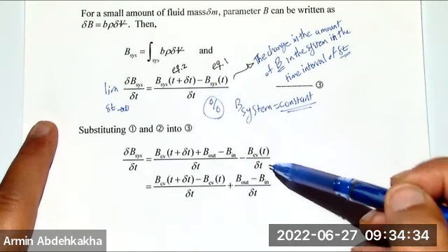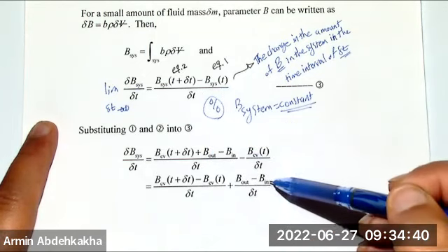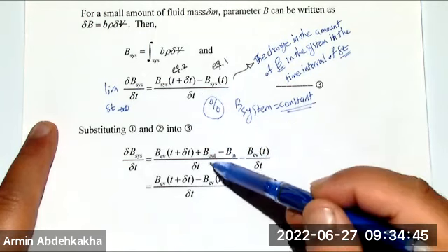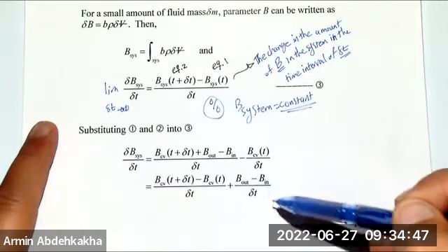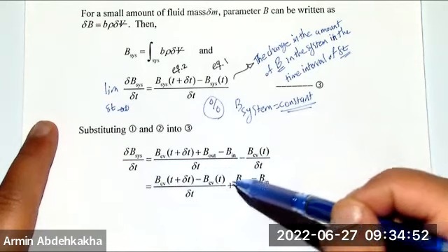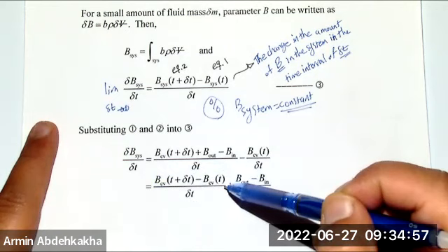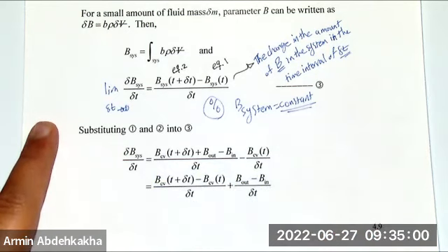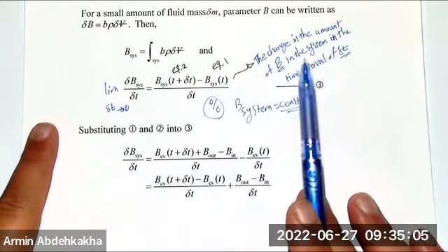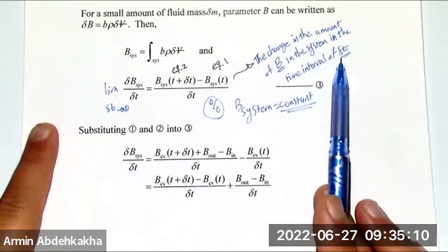Okay, perfect. So if I combine these two and bring B out and B in out of this term, then B out minus B in over delta t is equal to the time rate change of parameter B, or property B, in the control volume. So what is related now? It was the change in the amount of B in the system in the time interval of delta t.